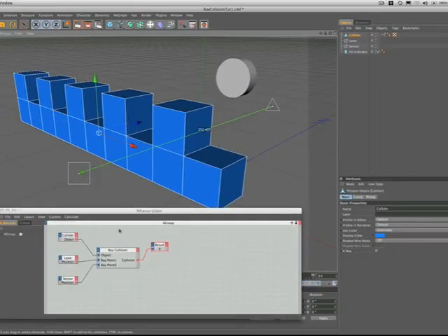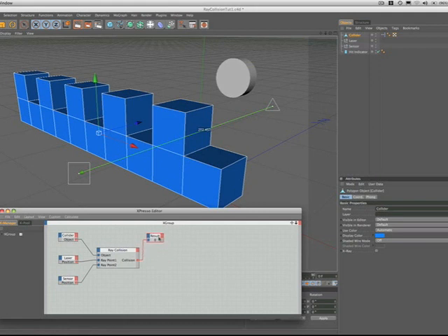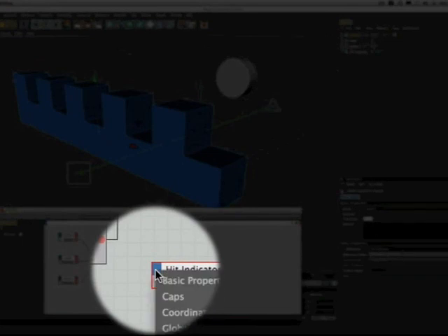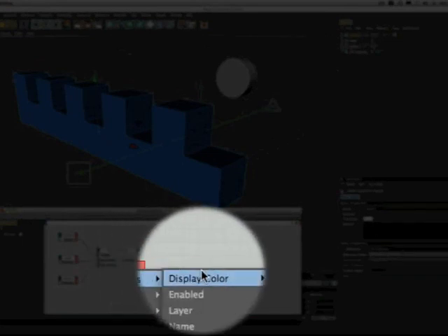So that's our first stage set up, and now we need to work with our hit indicator and make it change its colour from grey to red when there has been a collision. We'll drag that one in there, and this is actually our final stage because it's not a complex expression. So we'll just go to Basic Properties and select Use Color.